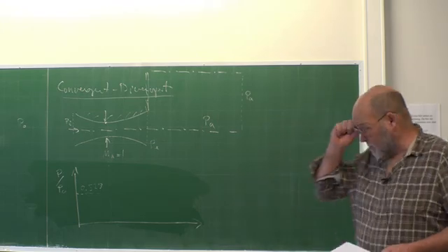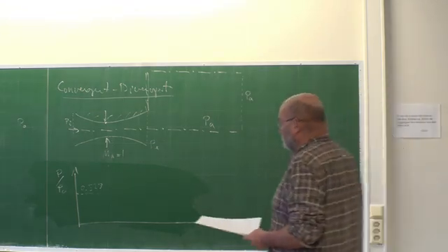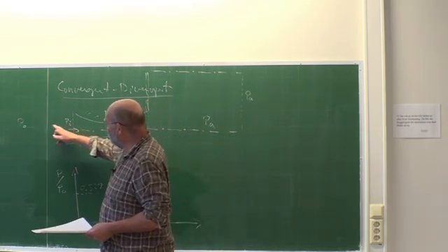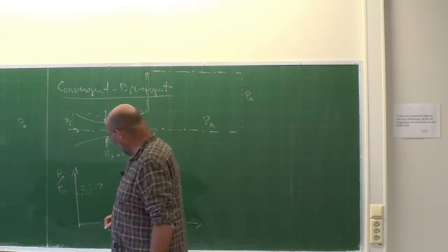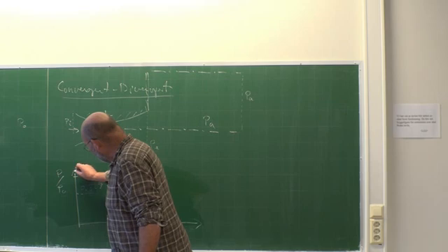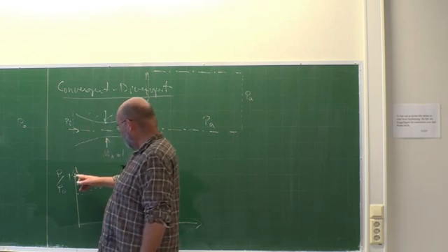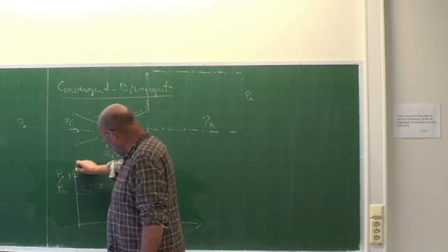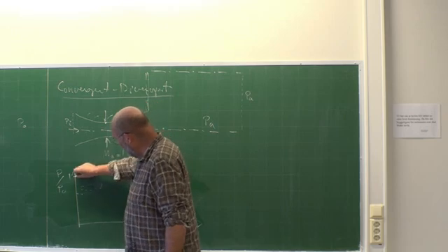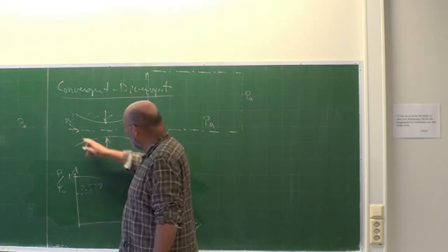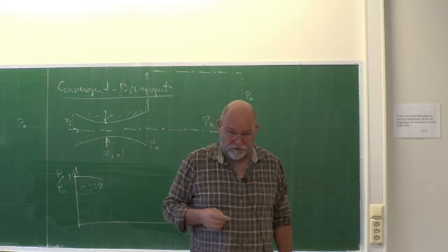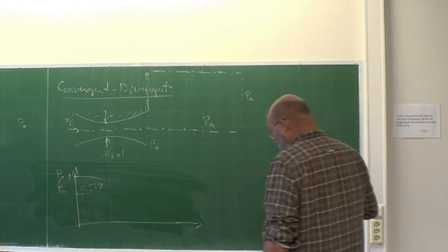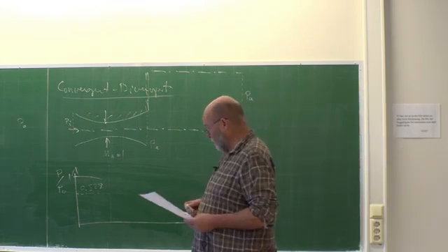So what's going to happen? Well, ideally, this value should be the same as that one. It's going to be a little bit of difference, but never mind. So I call it 1. It's actually a little bit lower, but never mind. So what's going to happen? Well, the pressure is going to go down when you have the flow inside this divergent nozzle. Of course it is. Speed goes up, pressure goes down, as it always will.